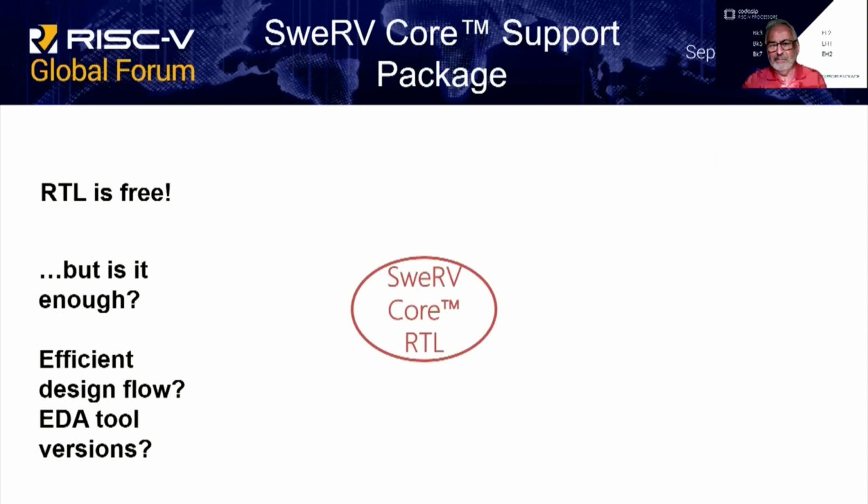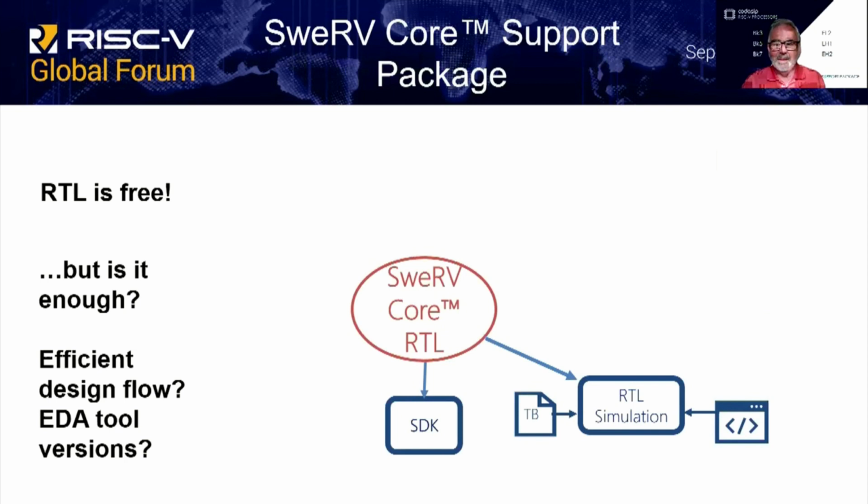So what do you need? Well, before we even think too much about RTL, you definitely need an SDK because you'll need to develop embedded software as well. You will need RTL simulation, you'll need a suitable test bench, and you will need to support the particular simulator you want to use.